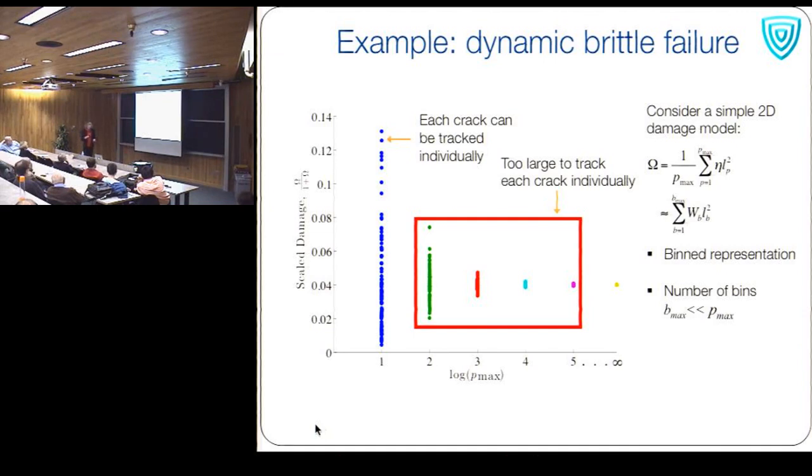The problem is that the damage assumption is probably not a good representation of that element anymore. What does it mean to have damage of a flaw population of 1? If you're down to that scale, you should be using a model that explicitly models each crack. Then you're in the domain where it's hard. We're kind of in this region.